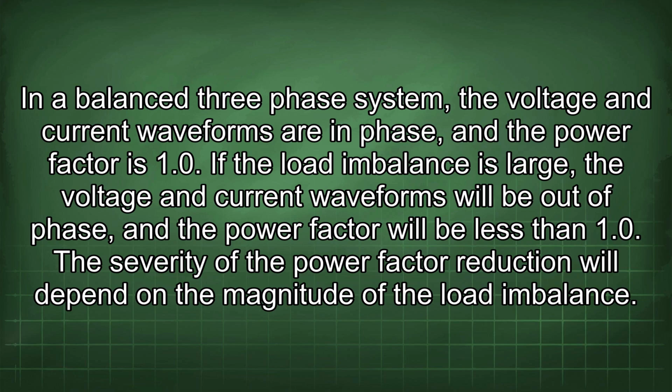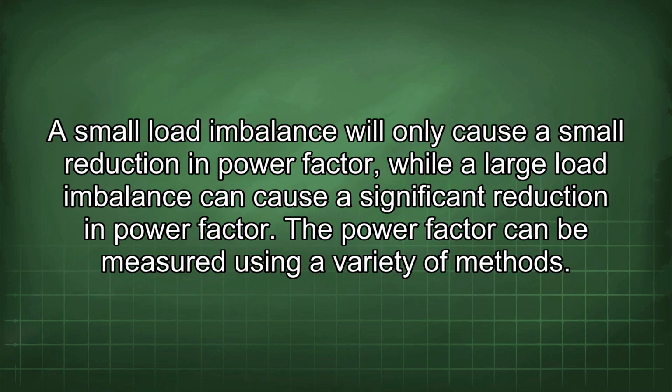If the load imbalance is large, the voltage and current waveforms will be out of phase, and the power factor will be less than 1.0. The severity of the power factor reduction will depend on the magnitude of the load imbalance. A small load imbalance will only cause a small reduction in power factor, while a large load imbalance can cause a significant reduction in power factor.